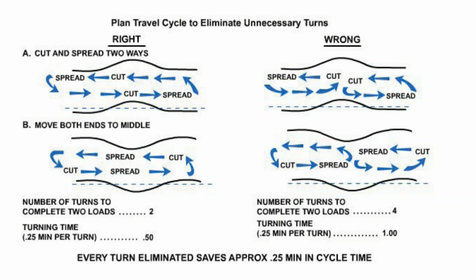We could do it with trucks. We take an excavator, we load the truck, we drive the truck 2,000 feet, and then we spread it. That's also inefficient. So we're going to find out that from about 300 feet to about 5,000 feet, about a mile, scrapers are going to be cheap. We should always compare and make sure that we have the right equipment. But in that 300 to 5,000 foot range, the scraper will almost always be the most efficient operation because you don't have as much handling.